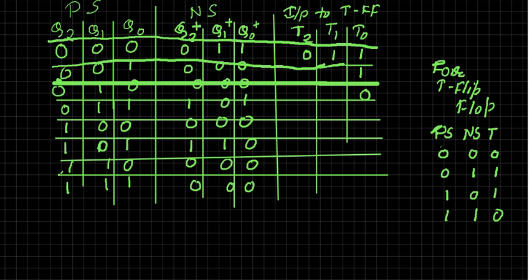The other way should be, okay, now the problem with this is, if it goes to invalid state, it has to go through multiple transitions to come back to the original state. There is no instant resetting which is happening with this approach. We haven't made use of any reset button there. But the other approach would be we can make use of that reset button which is usually there with the toggle flip-flop. So let's check for the conditions where the reset is required.